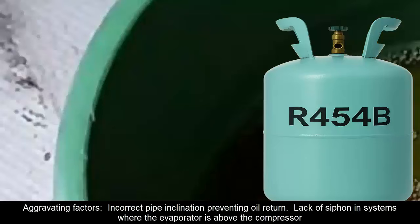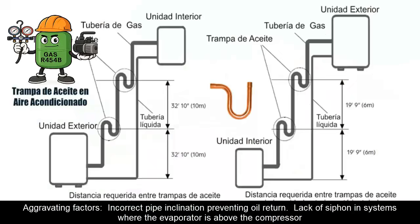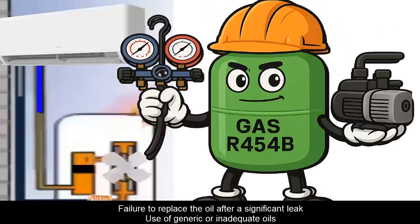Aggravating factors: incorrect pipe inclination preventing oil return, lack of siphon in systems where the evaporator is above the compressor, failure to replace the oil after a significant leak, use of generic or inadequate oils.